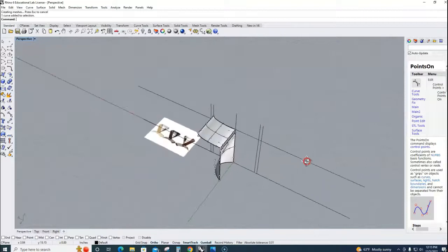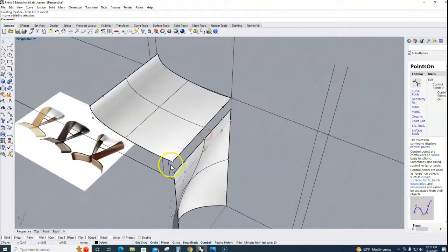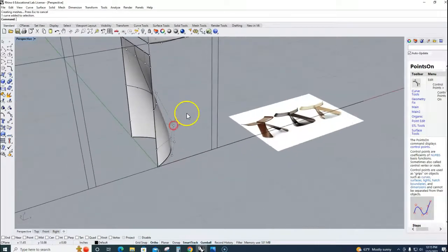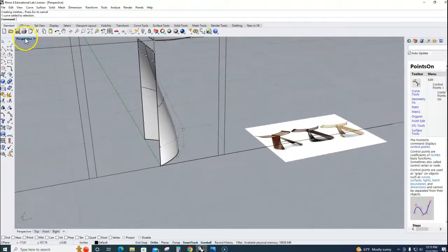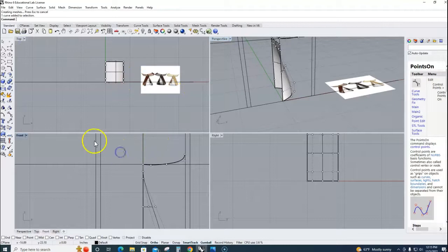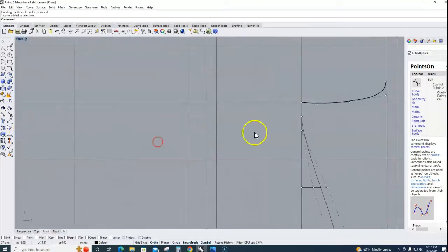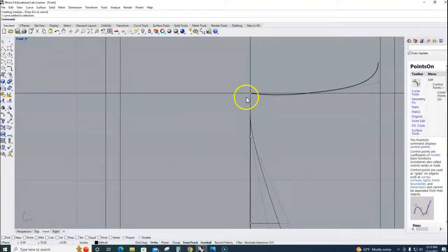Let's actually take, I'm trying to not change these 2 edges so that Rhino knows what to do, or at least gives me a clean fillet later on when I fillet that. So if I move this guy, I'm going to move both of these together because it'll be affected. So I'm trying to figure out a good, here I'm going to actually move that together too.